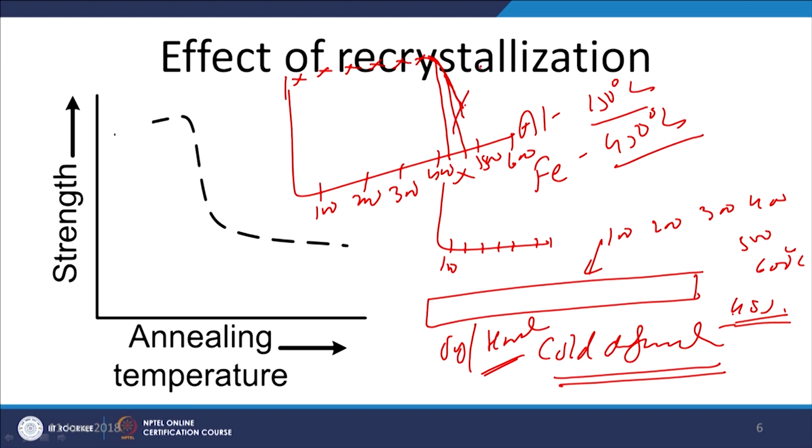450 degrees centigrade, and this is attributed to the recrystallization, which means the formation of new grains, which will be eliminating all work hardening effect that was there earlier. Eliminating all means reducing the dislocations from the plastically deformed metal and making it softer.